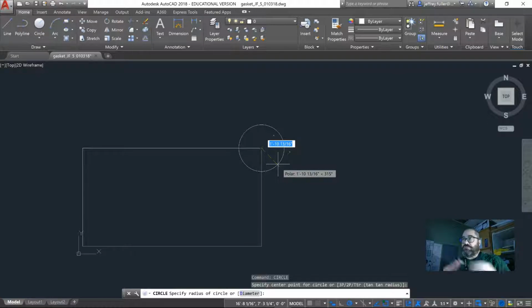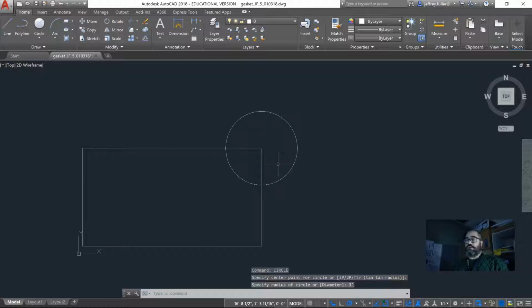Now naturally, from the beginning, it measures with radius. Whatever I type in here, I'm going to make basically a 6-foot circle. So I'm just going to type 3 feet inside of the dynamic input box and click enter. And it gives me a 6-foot diameter circle because it was measured from radius. And we know that diameter is 2 times radius.